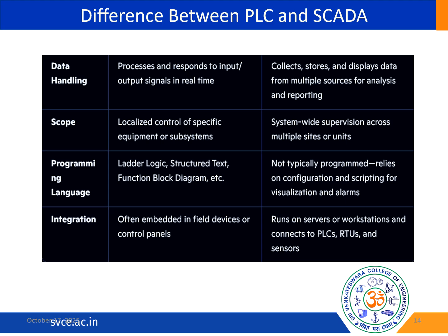Next, depending on the programming language, in a PLC we'll be using programming languages like ladder logic, structured text, function block diagram, and so on. And in a SCADA architecture, we will be using non-typical programming, which relies on configuration and scripting for visualization and alarms.